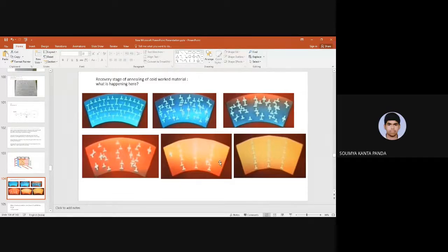Sir, a lot of edge dislocations again, but of the same sign, positive. Same sign. What are they doing? Sir, they are forming a tilt boundary. But what are they doing? Annihilating. I'm asking, what about this figure and this figure? Compare this figure with this figure and this figure. They arrange themselves in a particular fashion. Very good. They have arranged themselves one above another or one below another, right?